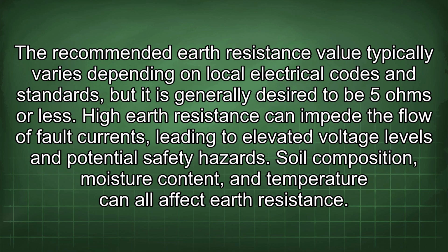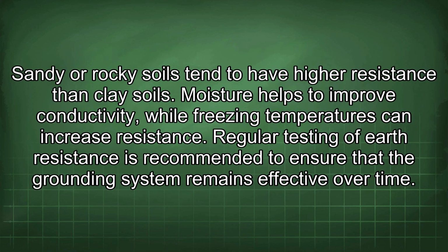High earth resistance can impede the flow of fault currents, leading to elevated voltage levels and potential safety hazards. Soil composition, moisture content, and temperature can all affect earth resistance. Sandy or rocky soils tend to have higher resistance than clay soils. Moisture helps to improve conductivity, while freezing temperatures can increase resistance.